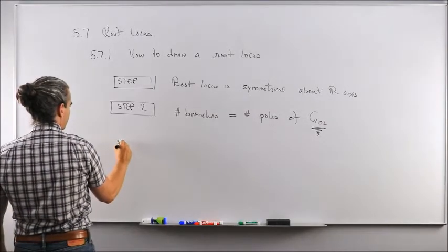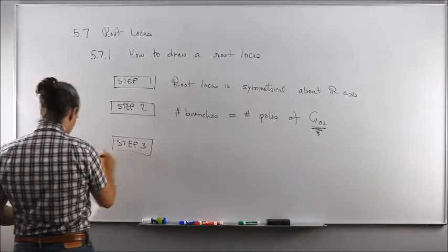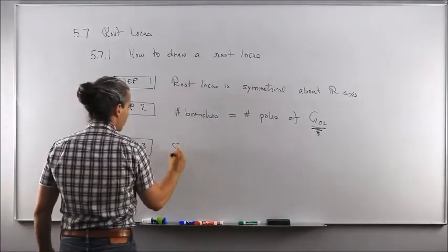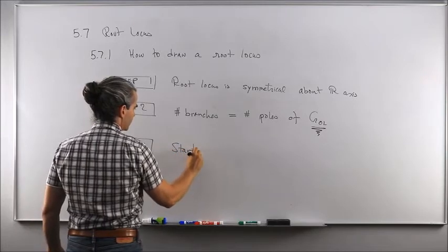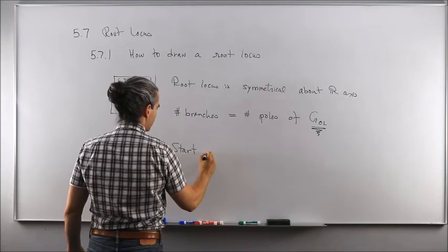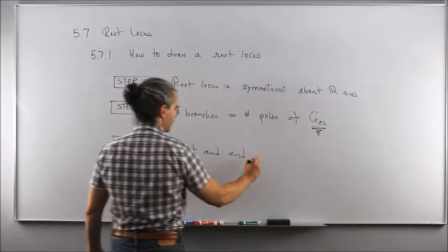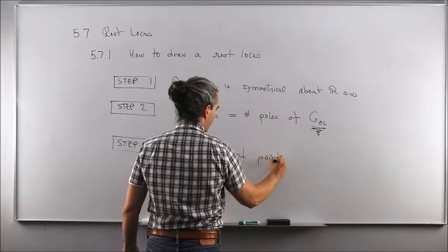Step 3. In that step, you need to determine where the root locus starts and where it ends.